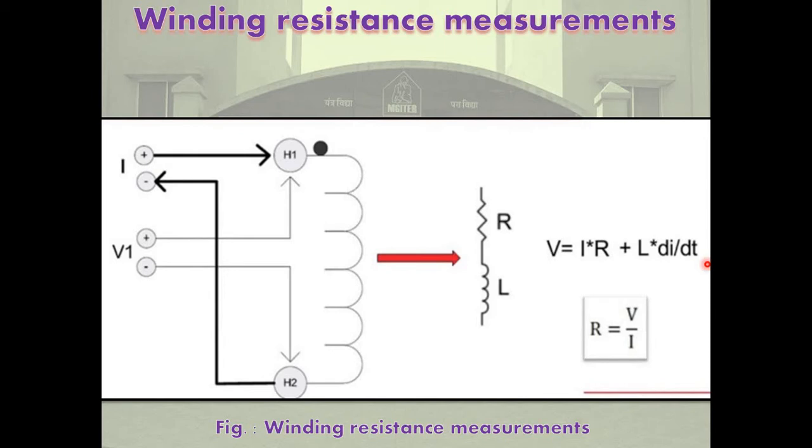Measurement of windings. DC resistance can be made with a Wheatstone or a Kelvin bridge. Alternatively, the volt-ampere method can be used for low resistance measurement. A heavy current of 100 amperes and sensitive meters would give accurate results. The test may be made when the transformer is cold or hot. Winding and oil temperature should be recorded when measurements are made. So this is the basic theory of measurement of winding resistance of a power transformer or any winding resistance.